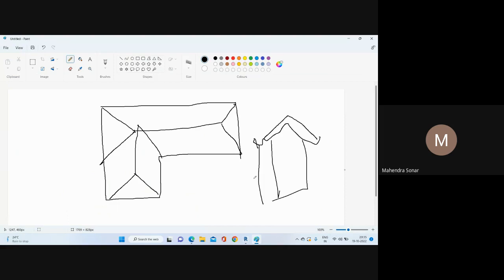Okay, so you need to model here, because when we represent this building, you need to give all details. In structural drawing, we do not design the gutter and drain pipe in detail, but you need to model it and just highlight it in your 2D drawing. Gutter by architectural drawings, then drain pipe confirm with architectural or suppliers. Okay, but we need to model here.